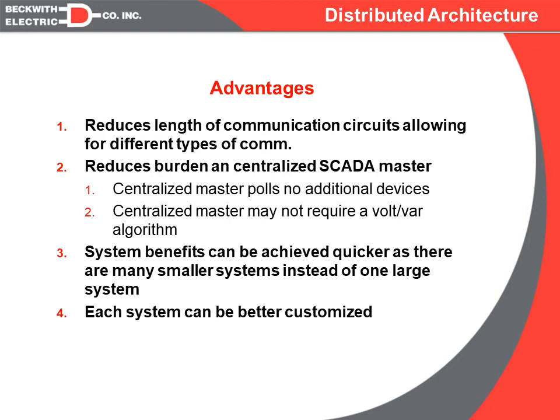communication options. So we can look more at mesh radio, and we can look more at unlicensed frequencies, because the distances we're communicating are shorter distances. We also don't put any burden on the centralized SCADA master, which can be an expensive proposition.